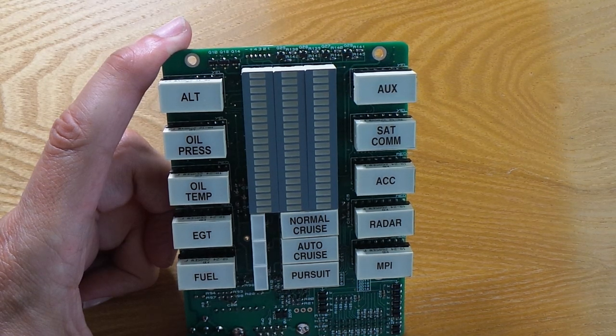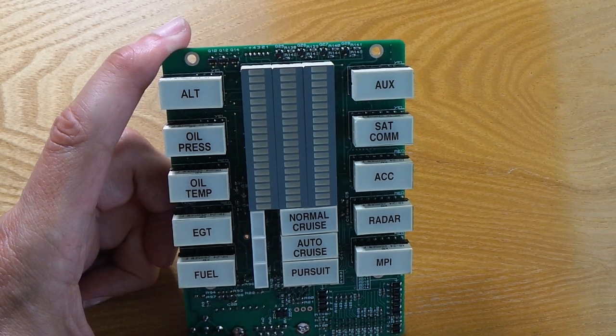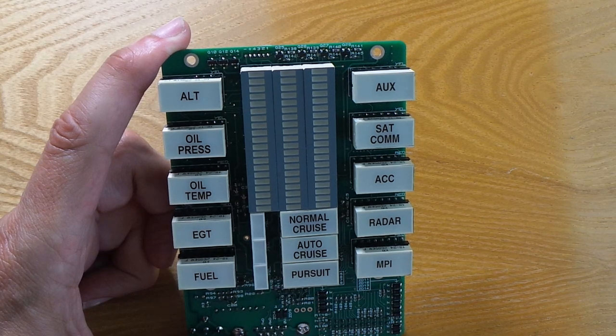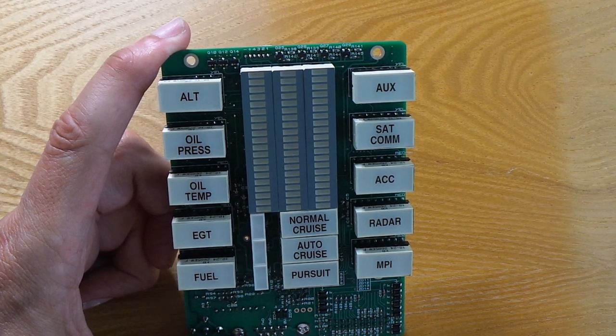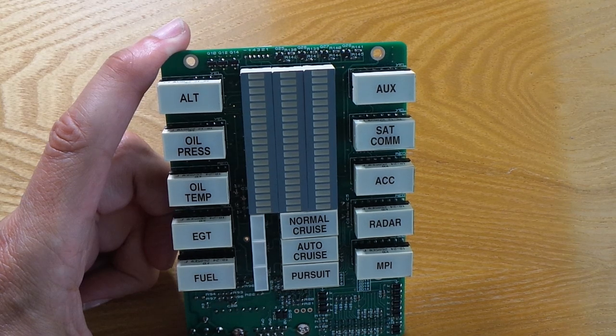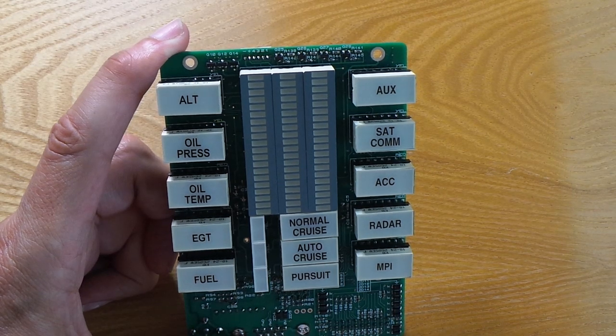The dash top indicators themselves can be programmed to switch off when the lights are on, that is if you have the lights connection connected, and that's something that has to be set in the programming, so that would have to be reprogrammed if you want to change that. The default setting is that yes, the dash top indicators do switch off when the lights come on. Another option is that you can program the dash top indicators to go off when you turn potentiometer number 2 right down to its minimum value. Again, that's something which can only be changed within the programming.